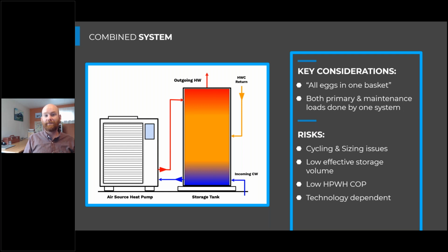But balancing valves to get balancing across multiple tanks alone is not typically adequate enough to maintain a good balanced tank arrangement, because we see flow rates vary from 1 GPM to 10 to 30 GPM, and those valves will only be balanced to a smaller flow range than that large flow range we typically see. It's a great question from Ian. Thanks for all those, and keep them coming.